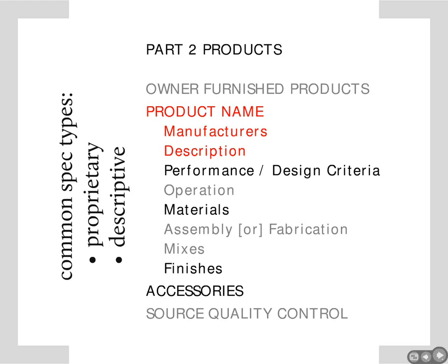For instance, in a wood window, you have choices of different wood species, or in the case of a clad window, what the cladding material might be. And then ultimately, whether or not you'll accept finger-jointed wood for interior. Right, depending on the ultimate finish, and then whether it is a factory finish or a field finish.